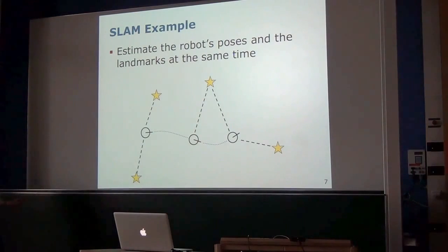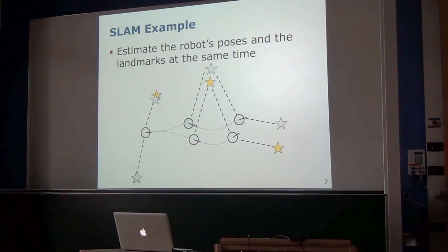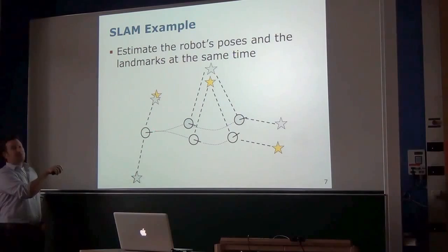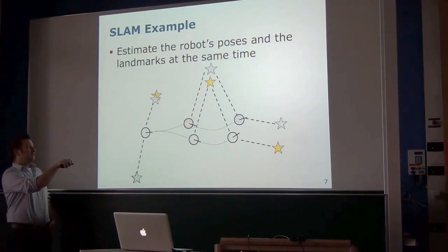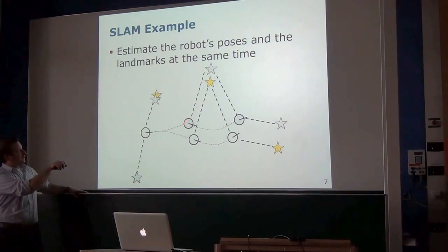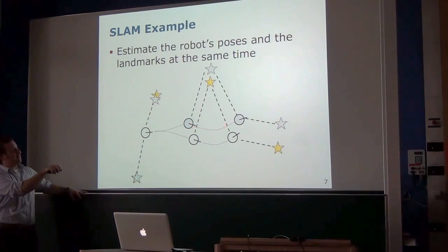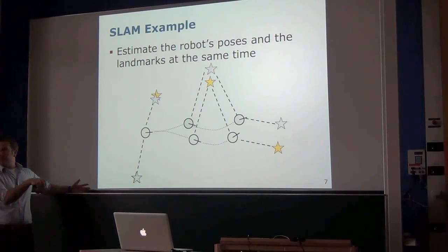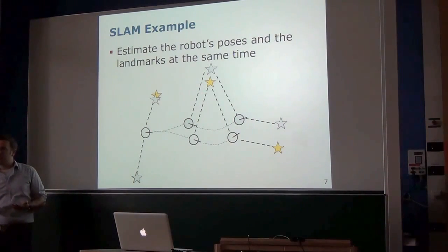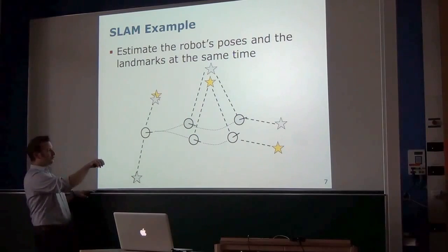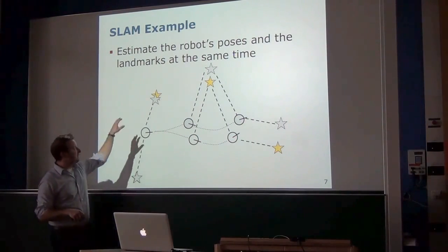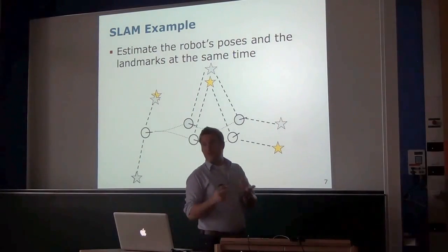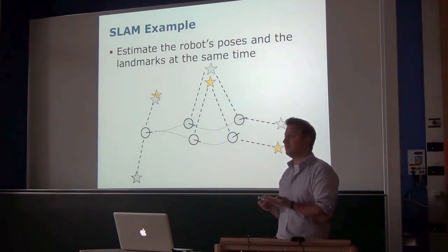So the robot moves through the environment, estimates landmarks and says, given what I measured while I moved through the environment, I think this is the pose of the robot at the first time step, the second time step, and then those landmarks need to be here. You can see that this doesn't really match reality, or there's a mismatch between the ground truth, which is this trajectory with those yellow landmarks, and those estimates the robot obtained. But that's natural, so the models of the environment are typically not perfect.